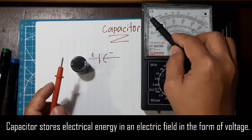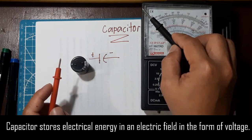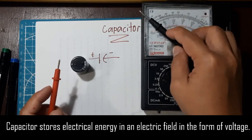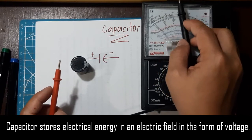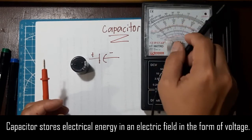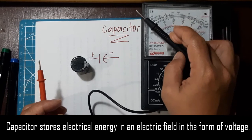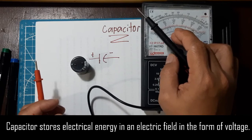So that signifies that the energy is being stored in our capacitor, and eventually it will go at rest towards infinite resistance. So it's storing and it's releasing the energy. So that should give us an idea that our capacitor is in good working condition. Otherwise, if the resistance goes to low resistance and it did not deflect back to the infinite reading, we can consider that our capacitor is short-circuited.